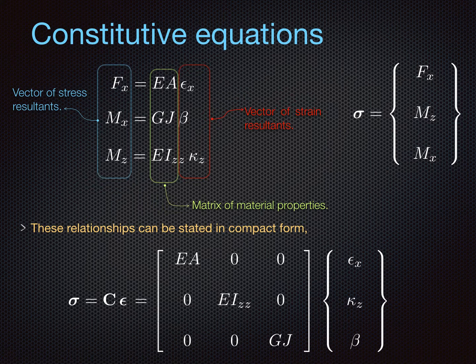If you apply, for example, a vertical load and a lateral load, the axial shortening of a column is coupled with the rotations and the vertical displacements of a beam that is supported by that column. So the examples are endless. Just remember that this uncoupling at the constitutive level does not necessarily mean that all these three problems are uncoupled. They're indeed coupled for the general case.